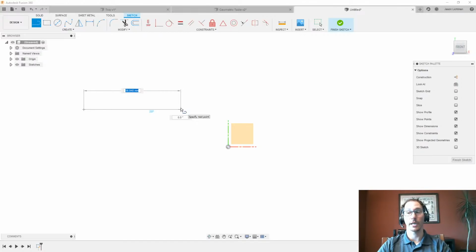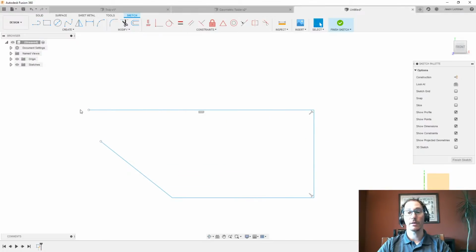to apply a constraint. And I told you later, we're going to talk about constraints in more detail. Just want to give you a little bit of a heads up that it's all going to tie in together. So I can create a line that's horizontal. I can create a line that's vertical, another one that's horizontal. But here's really the key. Until I connect everything together, I have what's called an open sketch or an open vector.